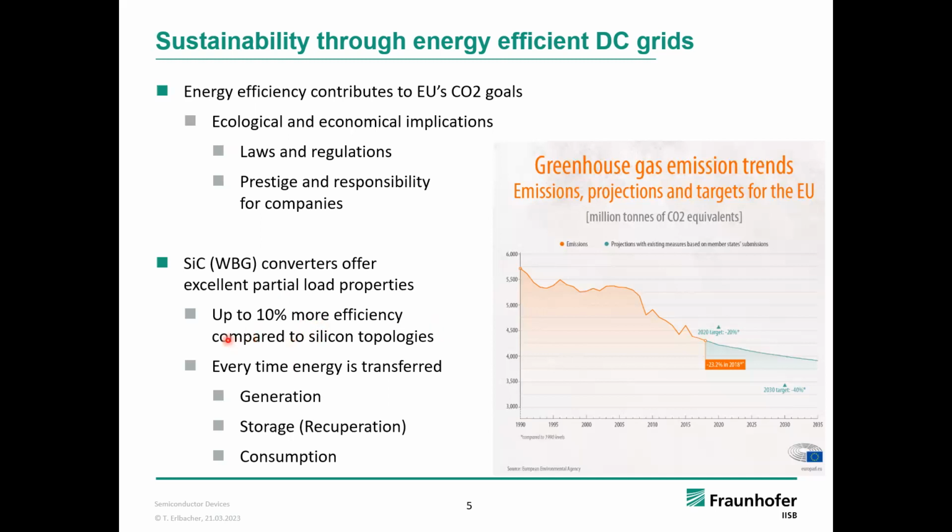Electric vehicle is the best example because usually you're not accelerating all the time when you're driving the car, but most of the time you're idling at somewhere maybe 20-25% of the load. And there, silicon carbide material, being a unipolar device, has a significant energy efficiency benefit over using silicon IGBTs. And this is particularly true if you're transferring and storing energy between generation and consumption, because you're incurring these losses multiple times.